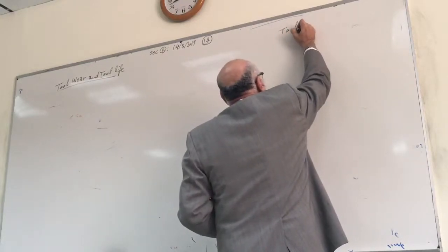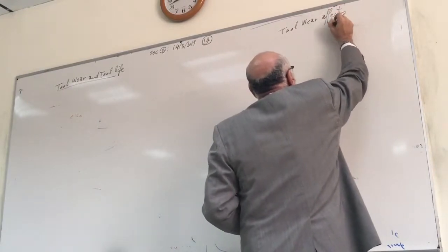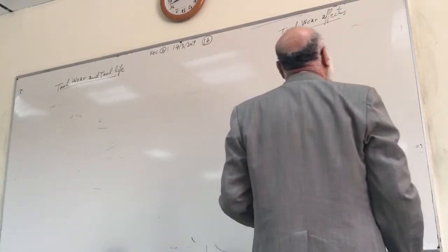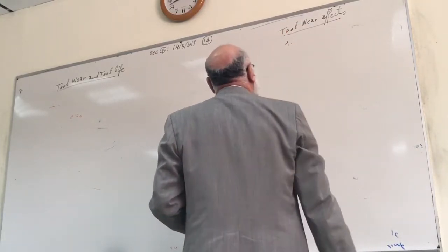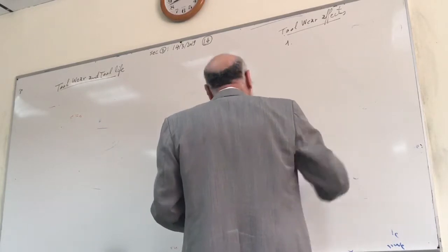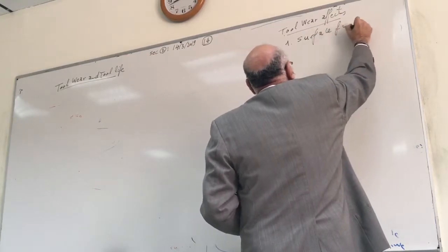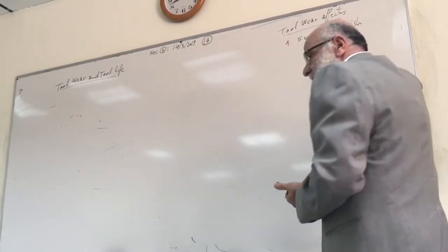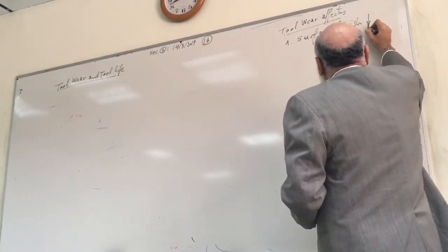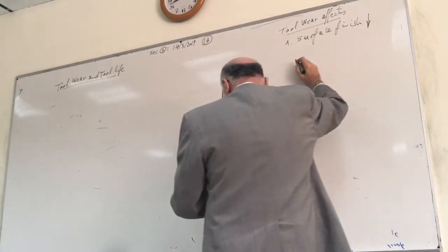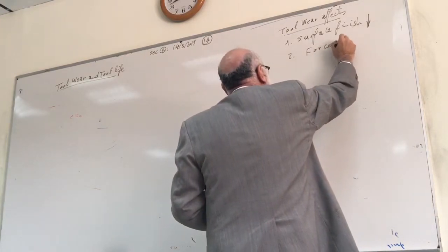Tool wear affects the following items or variables. Tool wear will affect the surface finish. When the tool wear increases, then the surface finish decreases. It also affects cutting forces, which will increase,